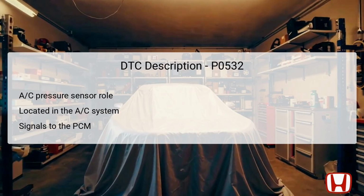The AC pressure sensor measures the refrigerant pressure to help manage the air conditioning's performance. This sensor is typically located in the AC system near the evaporator or compressor. It sends voltage signals to the PCM to inform it whether the refrigerant levels are adequate for optimal cooling. The sensor operates within a specific voltage range, and when the voltage falls below 0.24 volts, the DTC P0532 is set. If this error is detected, it typically indicates that there could be a faulty sensor, poor electrical connections, or problems within the wiring that need thorough investigation.